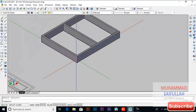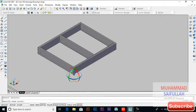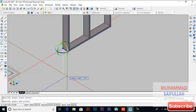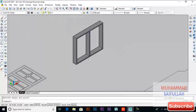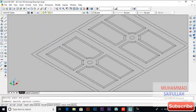So that's our gem. I will 3D rotate it. 3R for 3D rotate. Select object, enter, specify a base point here and click here. Now click here and go downwards for 3D rotation. So that's our gem. Now I will make a design.